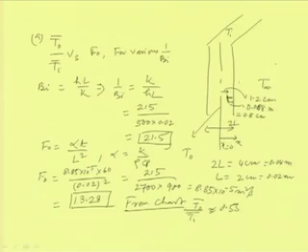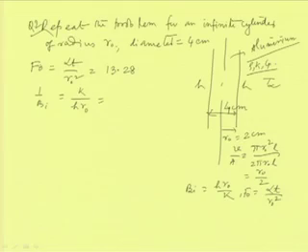And also the other part of the problem is maintained the same, like temperature T infinity is equal to 30 degree centigrade. Here Ti is taken to be 400 degree centigrade, and the h value is 500 watt per meter square per Kelvin. So, these are all maintained constant. Under that situation, 1 by Biot number is again 21.5.